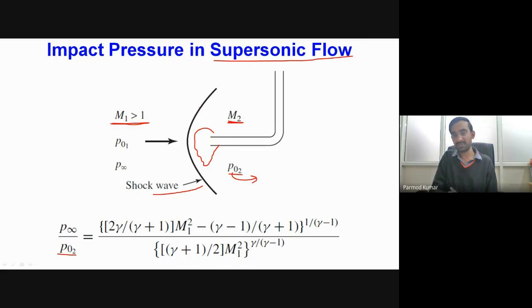Because of the change of the density, the corresponding value of Mach number on the left hand side of the shock wave and on the right hand side of the shock wave will change. So by considering the relationship between the Mach numbers, but more importantly, because we want to obtain the far field pressure, the Mach number we obtain will be our far field Mach number.